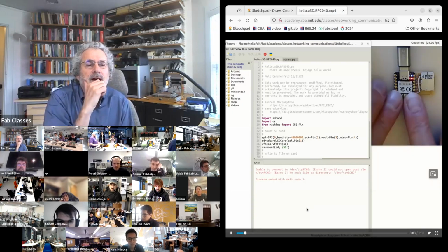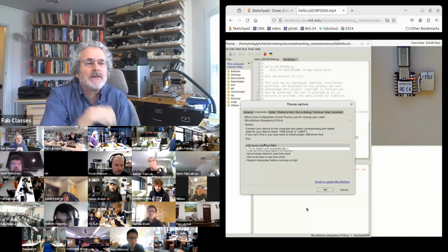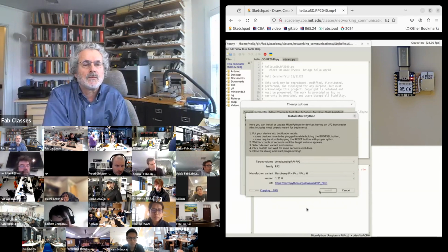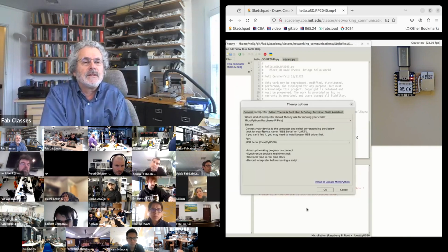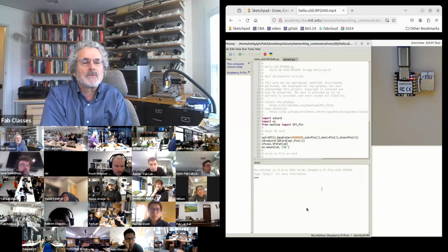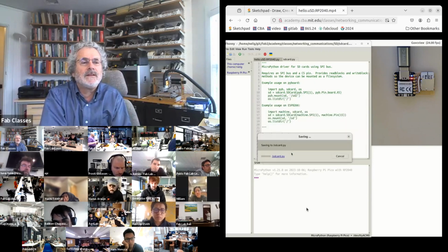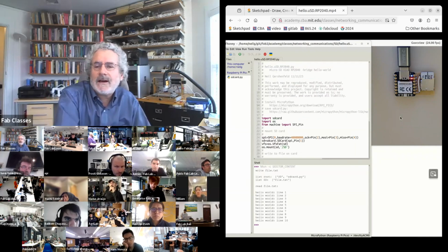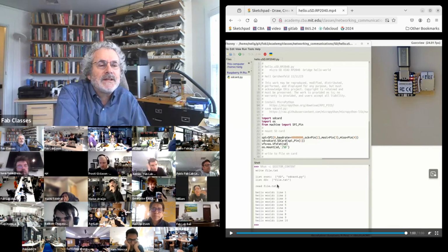And then here's a video of me going through the steps again. I reset the processor and load MicroPython on it. Then I have to connect to the correct port, which has moved. Then I need to tell MicroPython how to talk to memory cards, so I'm saving the SD card library on the RP2040. Now I run this program, and what happened didn't look that exciting. But let me show you the code.